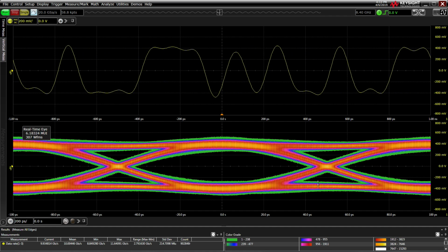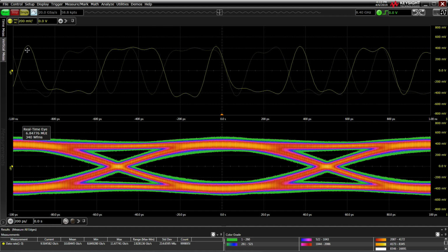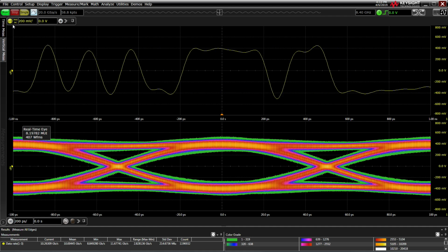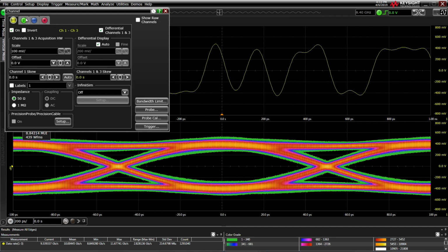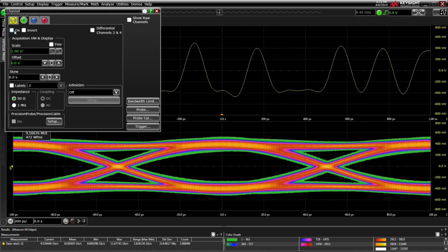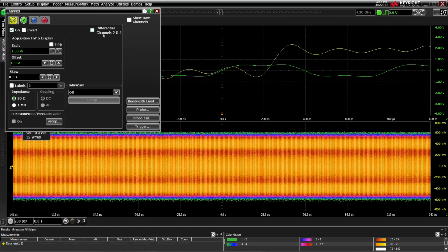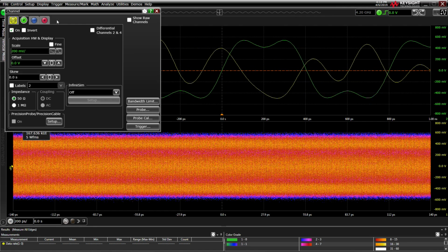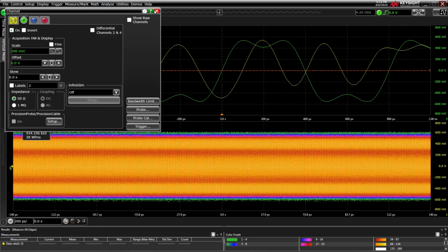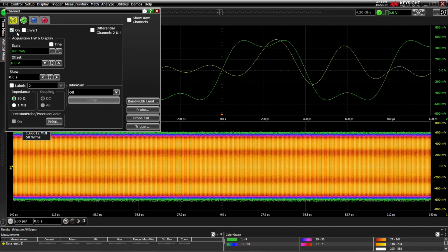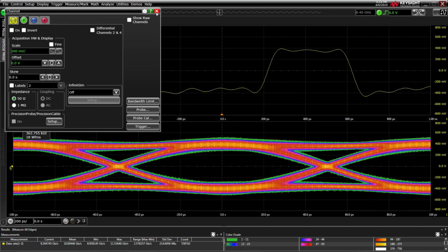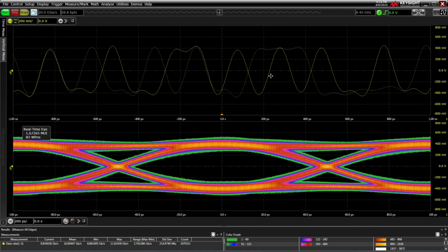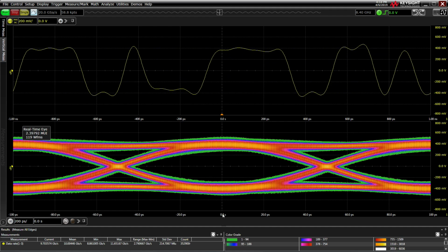Now this could have been because of a trigger point of view. Let me go ahead and turn on channel 2 so we can take a look at our trigger. This mouse is really slow. Let's see, there's our trigger signal. It should be there. Looks okay. Maybe the reason is because, there you go, that's our trigger. It looks reasonably good. I don't think that's a problem. Let's turn it back off so the eye diagram doesn't get messed up. There you go. So the trigger signal was certainly there. It was drawing the eye diagram of the trigger on top of everything, and of course that's going to mess everything up. But it looks very good.